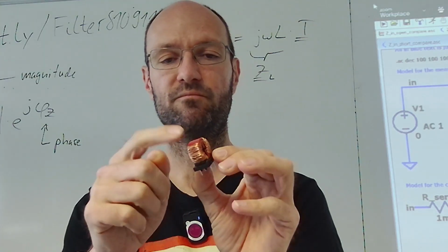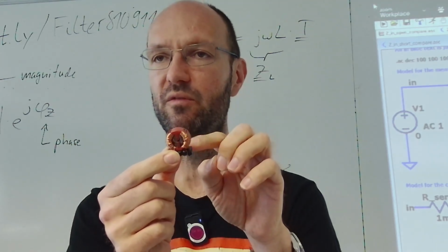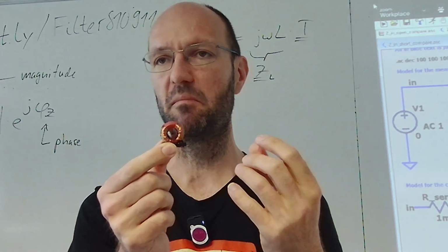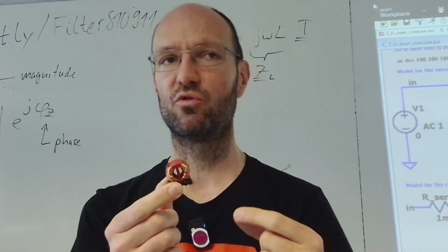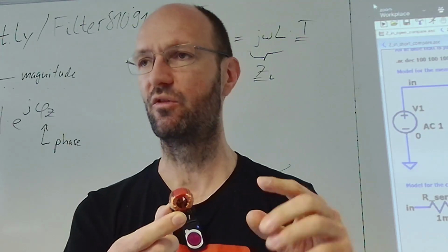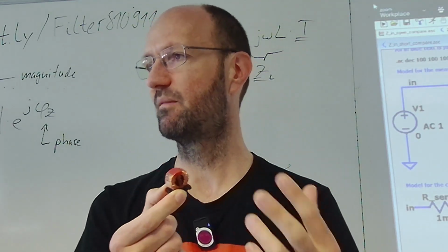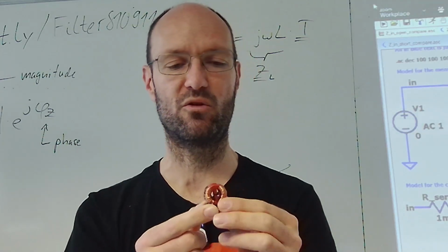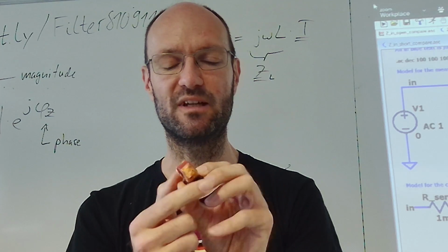And then the red stuff is the core. It's some ferrite material, so it's kind of a metallic magnetic powder, because you want to have permeability, but you don't want to have too much conductivity, because this would create eddy currents. But still at the end you want to have some losses inside there, because it should act as a filter and somehow dissipate the unwanted energy.